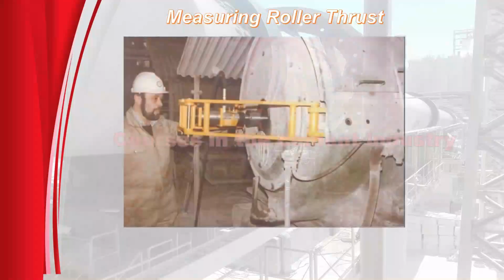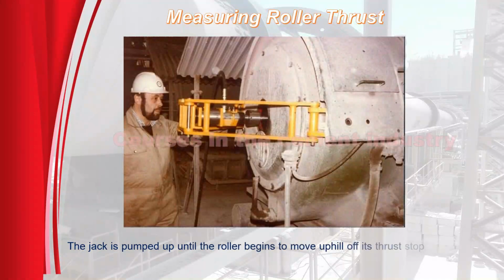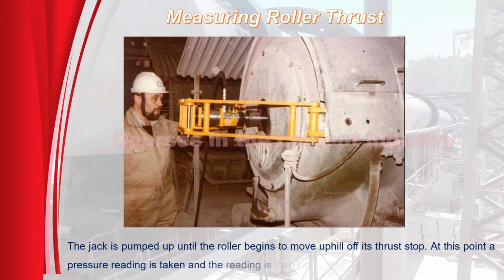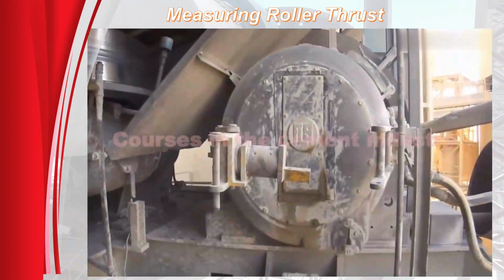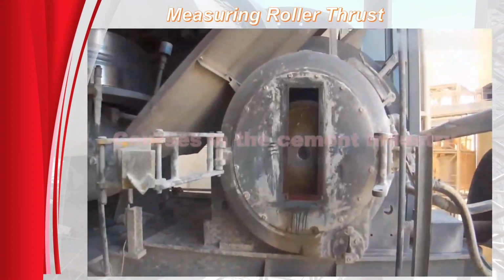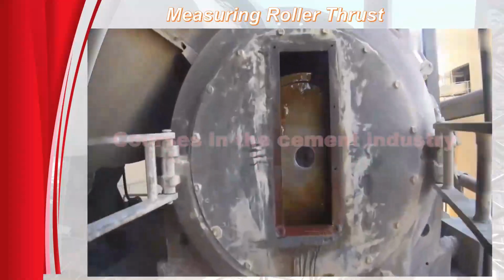As shown in this figure, the jack is pumped up until the roller begins to move uphill, off its thrust stop. At this point, a pressure reading is taken, and the reading is then converted to tons force. We see how to measure roller thrust in this video from the side. Also, note the equipment used, the measurement method, and the roller pressures.